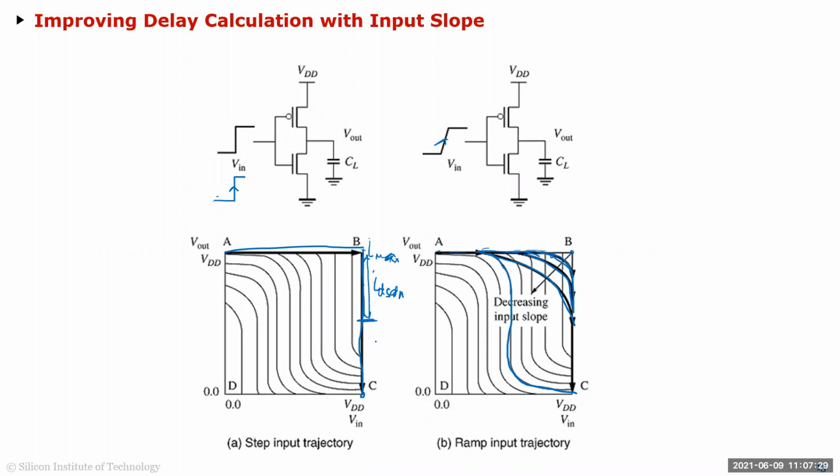Basically, the table actually has entries for different rise times. So obviously you have to have some granularity. With certain granularity, they'll say, okay, if the rise time is going from 1 picosecond to 100 picosecond, they might have 10 tables, and they usually call it what's called the timing arcs. And depending on these inputs, the delay will vary. The tool knows that for a certain load, what the delay of the output is going to be. So that will be the input of the next stage, and they will calculate it from that .lib file and so on.